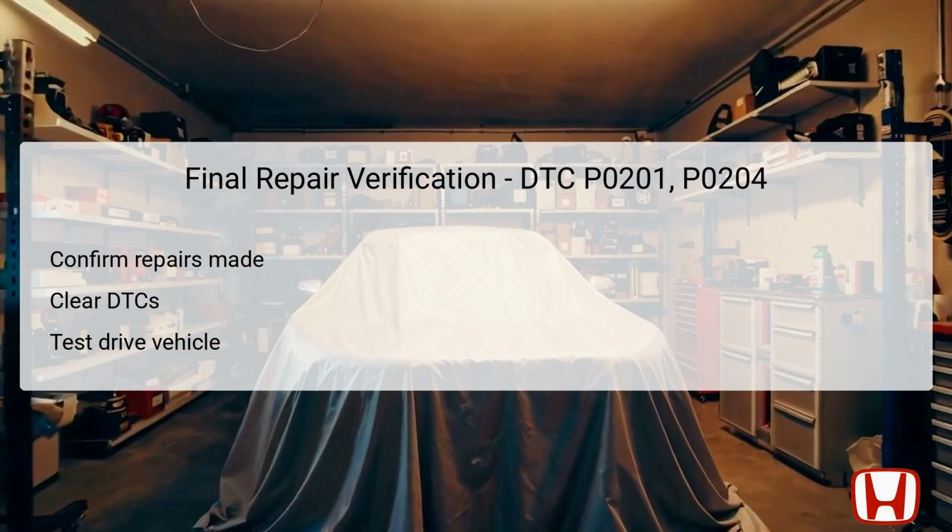Final verification of repairs is necessary to ensure DTC P0201 and P0204 are addressed effectively. After verifying and rectifying all potential issues, clear the DTCs using the Honda Diagnostic System, HDS, to reset any fault codes.